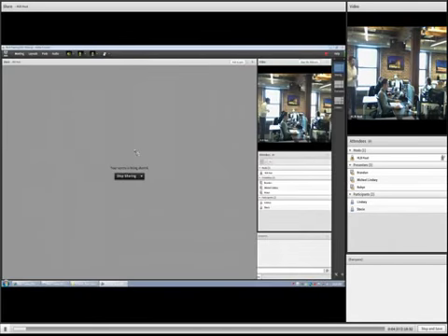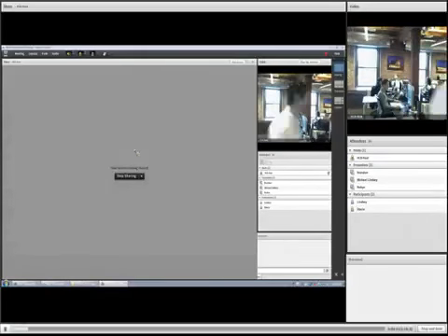Okay, that's actually good. So I see. That's one of the things about this HLB, the non-hosted versions: you have to be conscious of where they're going. Actually, it inserted at 0 feet, 0 inches above the finished floor. So you can actually change that elevation before you place one. Rather than chasing that one down, change your offset to 8 feet before you place it. If you start a lighting fixture, change that offset to 8 feet before you start placing. That will help.